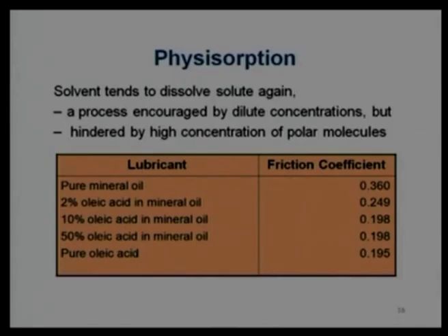So, that is why we require a little bit of boundary additives to get favorable results. We do not require the complete oil to be boundary additives, because that will be very viscous, difficult to pump, difficult to move. That is why we do not use 100% unless it is required by the situation.